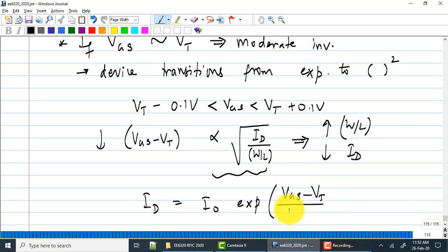You take a bipolar transistor, I increase the width of the transistor. What happens? Does the GM of the transistor change? It doesn't. Remember that the GM of the transistor is a full function of only the current. Similarly, does the VBE of the transistor change? It is approximately 0.65. What you will find is that if you keep going through the cycle, so this is in weak inversion.